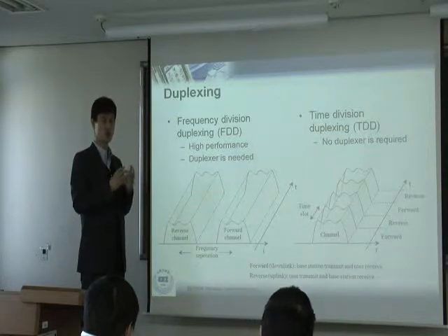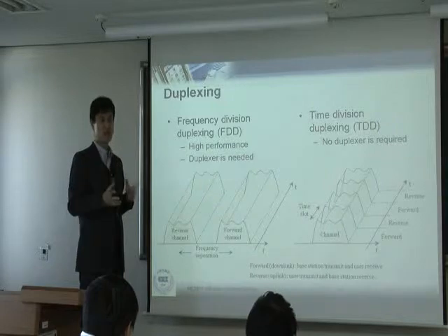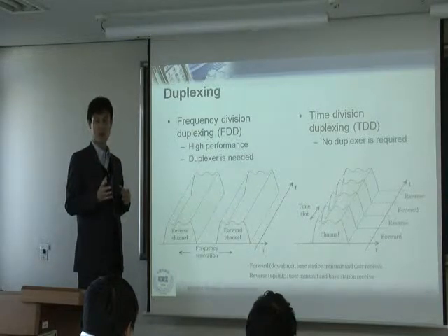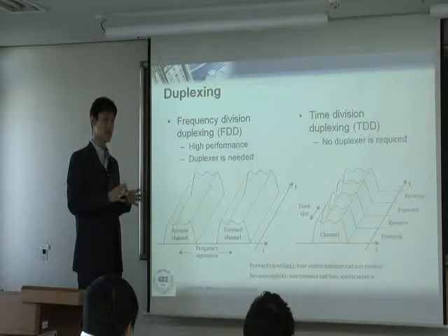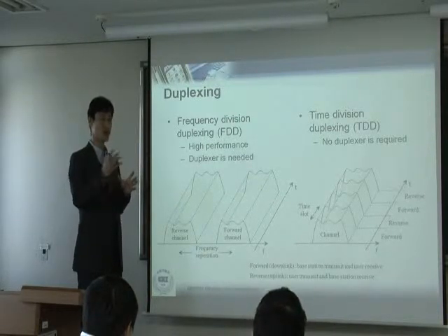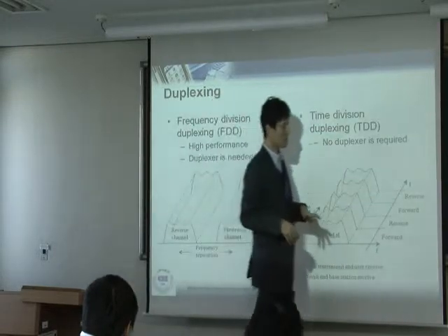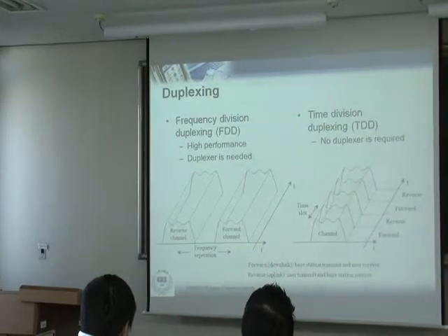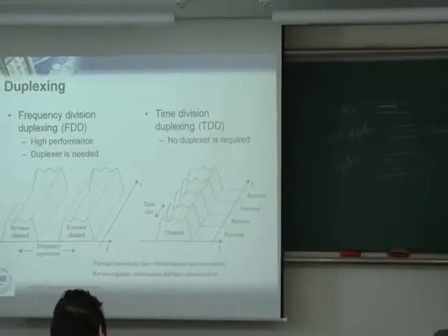receive. Your cell phone typically receives like minus 80 dBm, minus 90 dBm. Sometimes, if you are in a very, very good condition, minus 70 dBm and things like that. That's the receive power. Or sometimes minus 100 dBm. That's the power you receive. So now let's think about simply minus 100 dBm. Minus 90 dBm, let's say. This is your receive power.